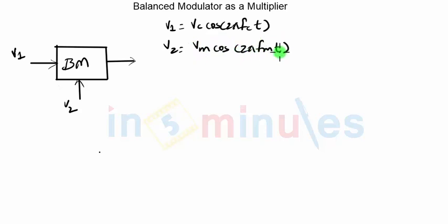Now, if you recall from the previous video clip, there were two diodes and we were using the non-linearity between the input and output signals. Because of the way we had made the connections on the input side, both the currents through the diodes were flowing in opposite directions. So the equivalent output current was the difference between the two. When we take that difference, all the similar terms were cancelled out and the terms differing in the negative sign were added.